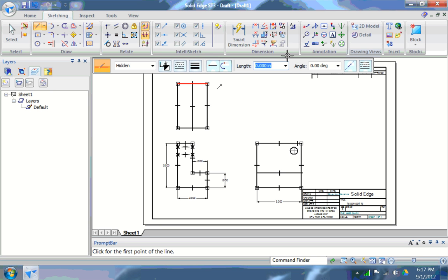We have to do the same up here. Okay, so what I'm going to do is go 0.5 of an inch down, like so. And that would bring me to the center of my circle, but I want to be at the top of it. So if you don't know the measurement, you can measure it here using your dimension tool, but I know that half of 0.5 is 0.25, so type that in and go like this, and then draw my line. Again, now I'm going to use 0.5 because that's the diameter. Hit that and click OK, and draw that across there to there, and there we have our hidden lines, like so.